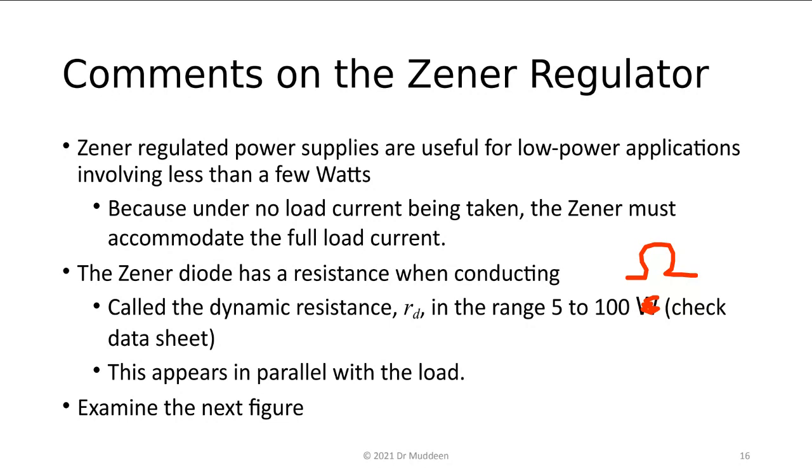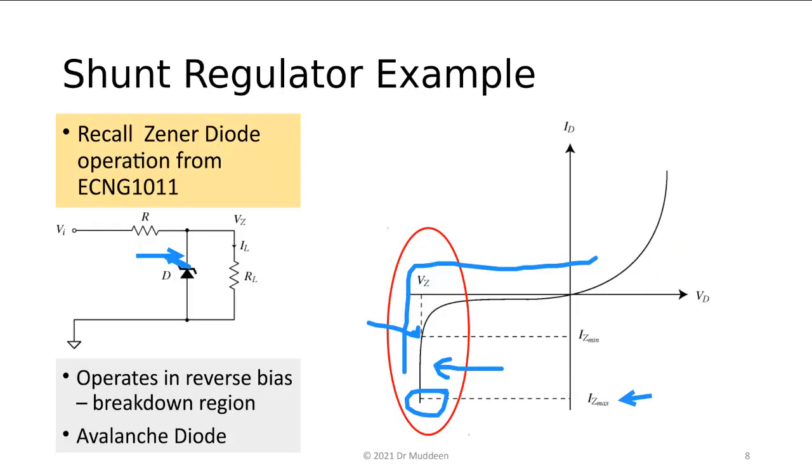Yeah, the forward bias, just now. When the diode is operating in a forward bias mode, a Zener operates pretty much like a regular small signal diode, a normal PN diode. So the forward voltage drop across it will be in the vicinity of 0.7 volts to maybe about 1.4, 1.5 volts. The forward voltage drop is a little bit more than a normal diode because of how the PN junctions are doped in the Zener diode. It's different from, let's say, a rectifier diode, for argument's sake.